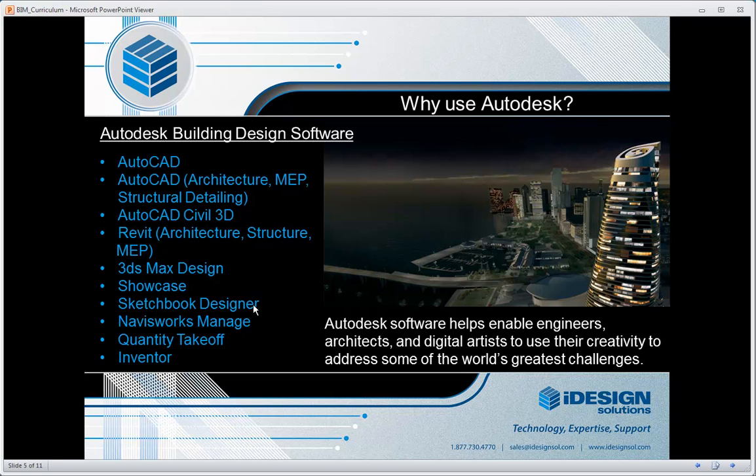Now, further along, once you're getting a little bit more familiar with the software, you might hear names like 3ds Max Design or Showcase, Sketchbook Designer. These are important applications to know about because they enhance your ability to create powerful presentations. So 3ds Max Design and Revit work very nicely together in the fact that you can export your BIM model into 3ds Max and your materials will stay, the lighting will stay, and you can manipulate things a little bit further and get a higher value presentation out of a 3ds Max Design render.